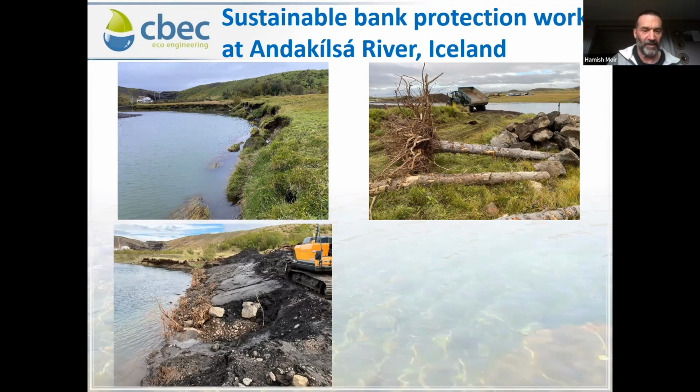This is a sort of nice real world cross section of the design. So here's the lower tier of trees below bed level with the trunks running into the bank here. Here's the second tier up here. Here's the sort of gravel cobble foundation material that they're set into, and then the boulders that are providing the ballast to hold them in place. And then there's the reprofiled soil. And once that's been done, we reinstate the turfs, here's all the turfs stored up here.